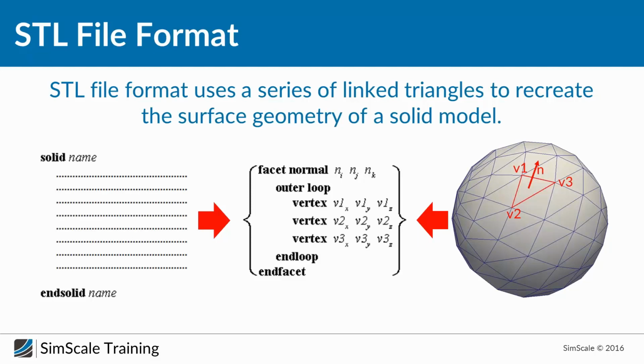And now a question by Thomas. Does the element size in STL tessellation affect in any way the mesh element size? No, Thomas, in theory not. Mesh size is only defined by your settings, but if, let's say, your STL tessellation is coarser than your mesh, you cannot refine the mesh any further than that, which makes sense. I hope you got it.